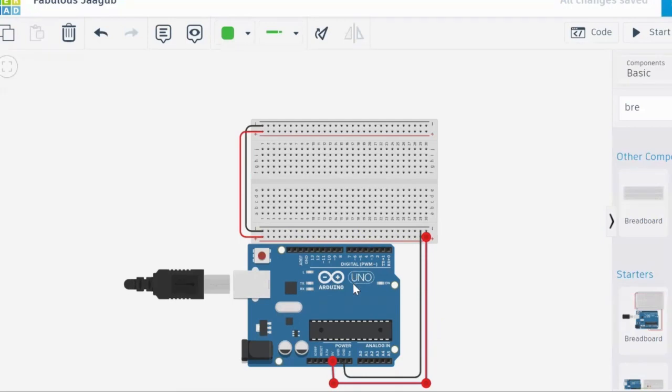If you are really a fresher and have never taken an engineering course, let me quickly introduce you to the breadboard also. In the breadboard, your entire row, this one, is shorted or connected. As you can see, it falls under the same line. Similar for this, and this. And here in the middle, entire columns are shorted or connected.